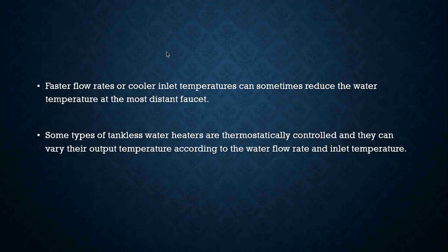Faster flow rates or cooler inlet temperatures can sometimes reduce the water temperature at the most distant faucet. Some types of tankless water heaters are thermostatically controlled, and they can vary their output temperature according to the water flow rate and the input temperature, which is another reason why we are going more towards on-demand water heaters.